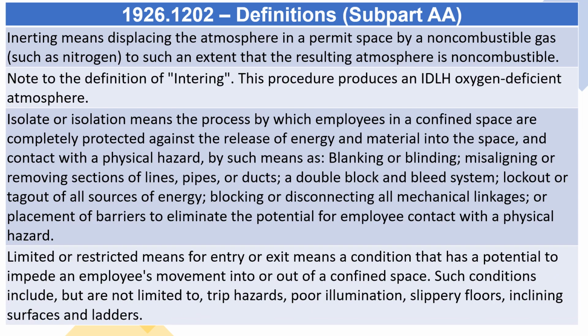Inerting means displacing the atmosphere in a permit space by a non-combustible gas, such as nitrogen, to such an extent that the resulting atmosphere is non-combustible. Note to the definition of inerting: This procedure produces an IDLH oxygen-deficient atmosphere.